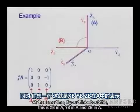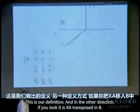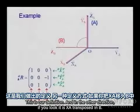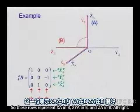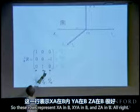At the same time, if you think about this, this is XB in A, YB in A, and ZB in A. This is our definition. And in the other direction, if you look, it is XA transpose in B. So if you take XA and express it in B, it's going to be 1, 0, 0 transpose. So these rows represent XA in B, YA in B, and ZA in B.